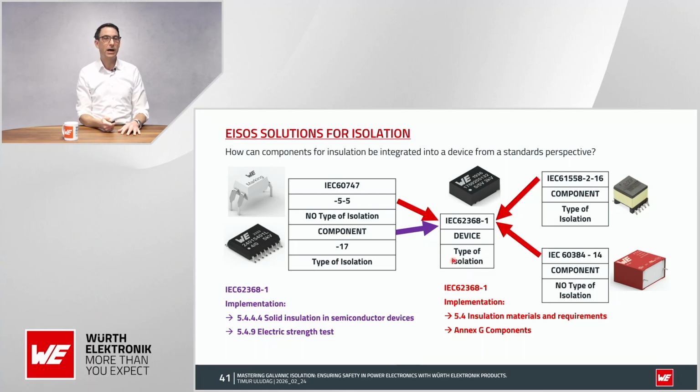So how can we then implement an optocoupler or a digital isolator? The optocoupler you can treat in the same way as a capacitor. There is an Annex G component, and therefore you can integrate it. But be aware, also an optocoupler has no information, if you read the standard, that says it is functionally isolated, reinforced, or basic isolated.